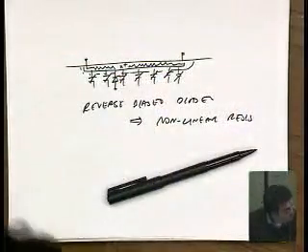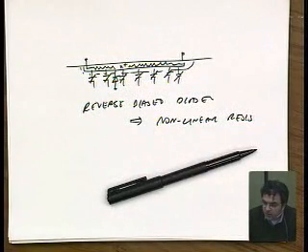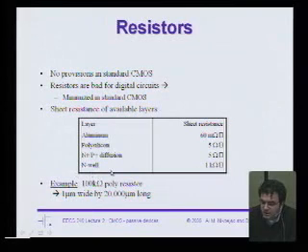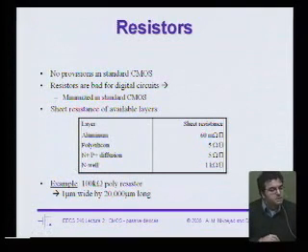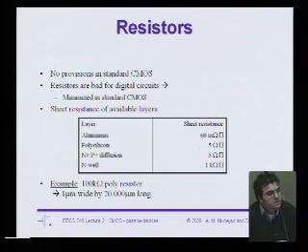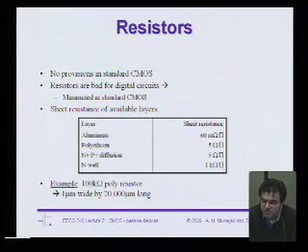Okay. How about N-well resistors? Switch back to the laptop. You can see that the nice thing is now, because the N-well is much more lightly doped, you get quite a bit of resistance, on the order of kilo ohms per square. So clearly this seems like the best way to build resistors, but it has the same problem. It has a voltage coefficient because it's a reverse bias junction. Okay.